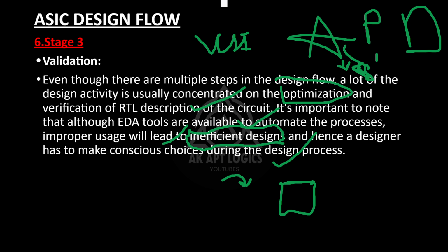We have to use those components, and we have to design the code for the components which are not available in the market. We are going to design RTL code in the behavioral model for that module, and we're going to verify that particular code using the TB. After everything is okay, we are going to convert that behavioral model design into the RTL or the gate level model,